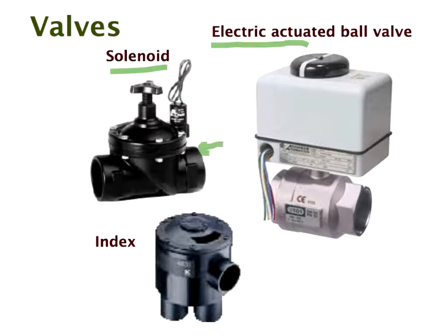So if the valve's normally closed, it needs a certain amount of back pressure for it to stay open. And once that back pressure drops below a certain level, a couple of psi, the valve will close, and then the pipeline might stay full, and it can freeze.